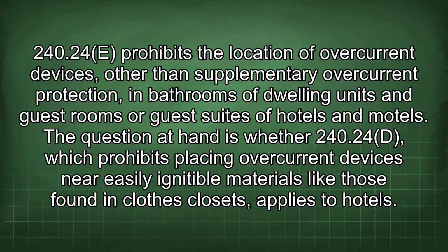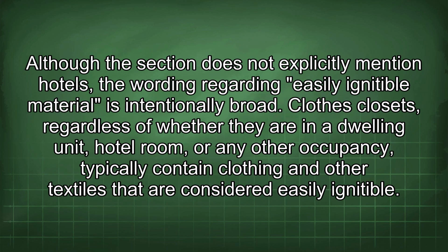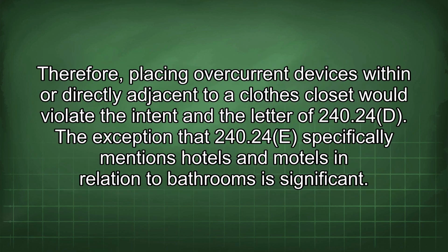The question at hand is whether 240.24(D), which prohibits placing overcurrent devices near easily ignitable materials like those found in closed closets, applies to hotels. Although the section does not explicitly mention hotels, the wording regarding easily ignitable material is intentionally broad. Closed closets, regardless of whether they are in a dwelling unit, hotel room, or any other occupancy, typically contain clothing and other textiles that are considered easily ignitable. Therefore, placing overcurrent devices within or directly adjacent to a closed closet would violate the intent and the letter of